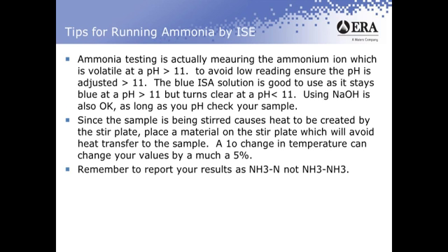The final point is that technology has advanced so that a lot of the manufacturers make what's called a high-performance electrode. And these high-performance electrodes allow you to get much lower readings of ammonia. However, they're significantly more sensitive and they do drift fairly easily.